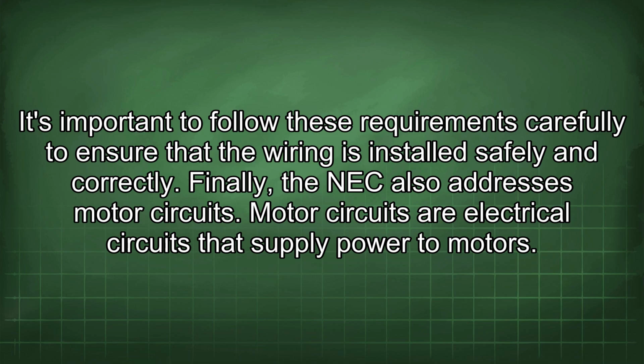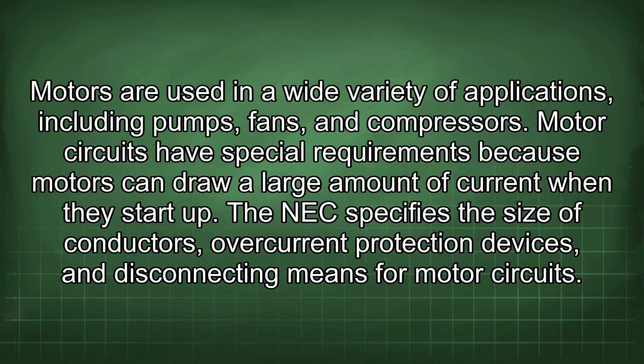Motor circuits are electrical circuits that supply power to motors. Motors are used in a wide variety of applications, including pumps, fans, and compressors. Motor circuits have special requirements because motors can draw a large amount of current when they start up. The NEC specifies the size of conductors, overcurrent protection devices, and disconnecting means for motor circuits.